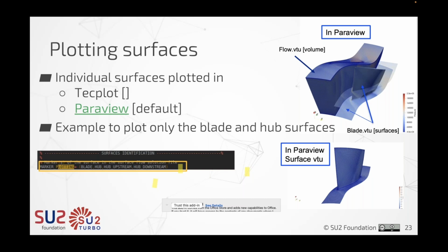So for large bypass ratio engines, it's customary practice to do that. For turbomachinery like centrifugal compressors, such as turbos for cars, you can have a scalar value, but for the big engines it's basically standard practice to have a profile.